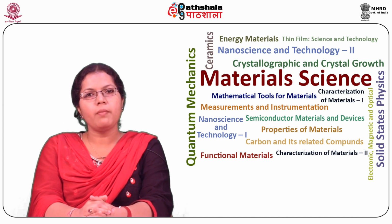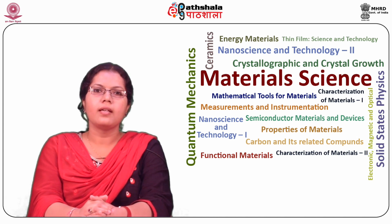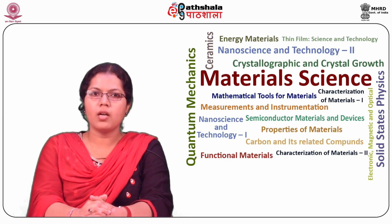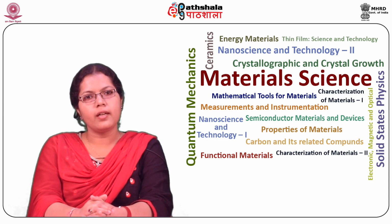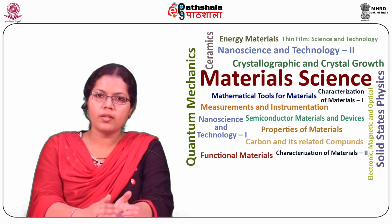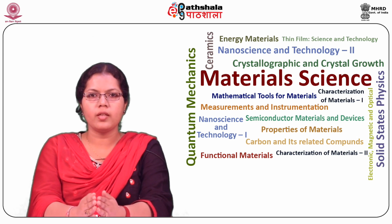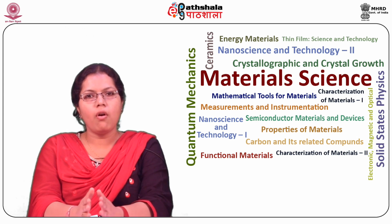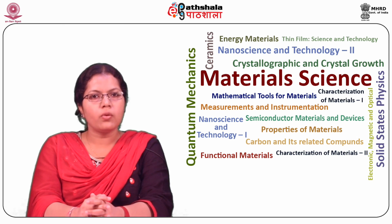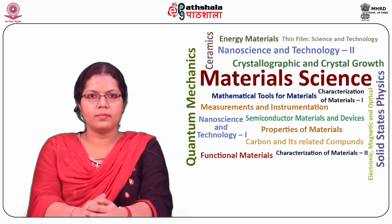When we use ferromagnetic materials, the value of permeability and hence inductance is dependent upon flux density, which in turn depends upon the current flowing in the coil. Hence, the inductance of an inductor constructed with ferromagnetic cores depends upon the value of the current passing. In order for inductance to be independent of the current passing, air-cored coils should be used for standards of inductance.